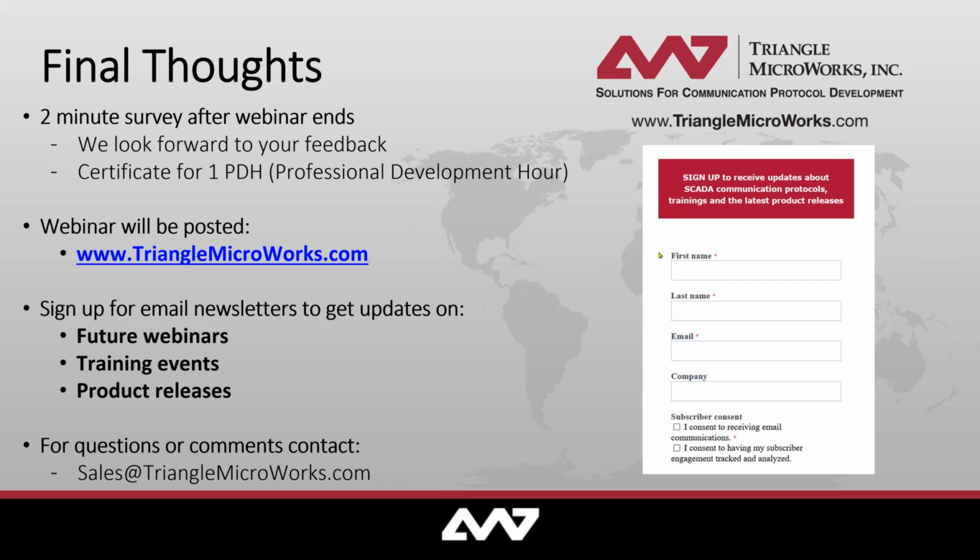Okay, thanks, Jackson. Next question can go to either Jackson or Christoph. If the SCD file was created, for instance, with IET 600, would it be compatible with this tool? Okay, I can take that. I think I answered it already in the chat. Basically, the compatibility with the tool, okay, there's the standard compatibility. So if IET 600, which is the system design tool from ABB, for those that are not familiar with it, creates an SCD file that is compliant to the standard, our DTM will be able to import that and use it.